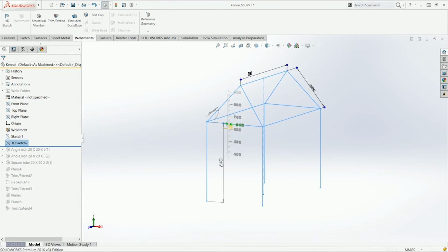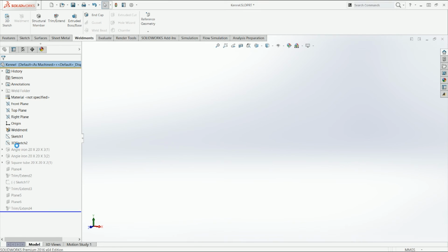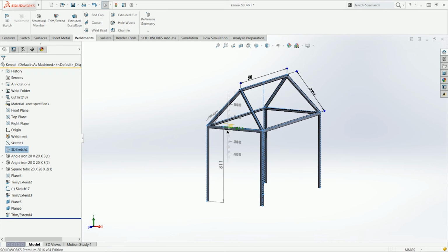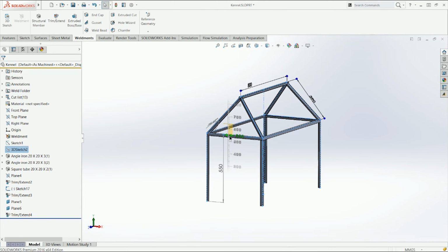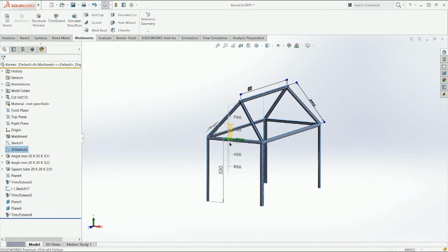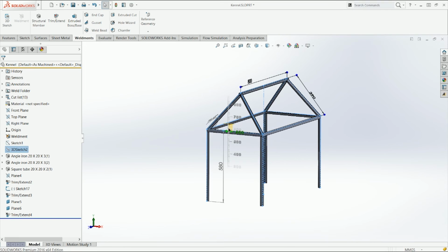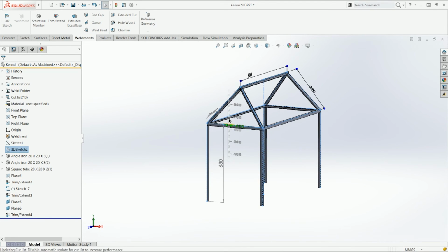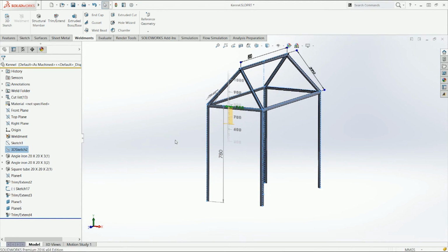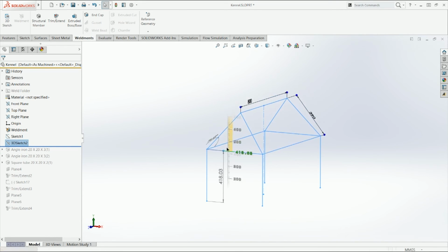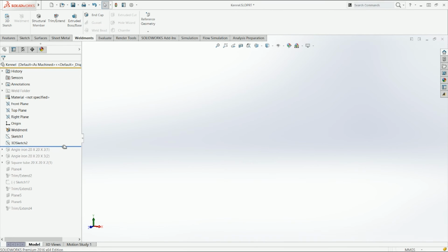What that's gonna allow me to do is edit this part without having to wait for everything to calculate, because you could also just do that within the SolidWorks edit part mode, which is just a regular part mode. But the bad thing is that it's trying to calculate as it goes. So the difference there is the time it takes you to see a change. Well, if you just drag this, you're just omitting all the calculation that you did before and just click and drag, and that's what the blue bar works for.